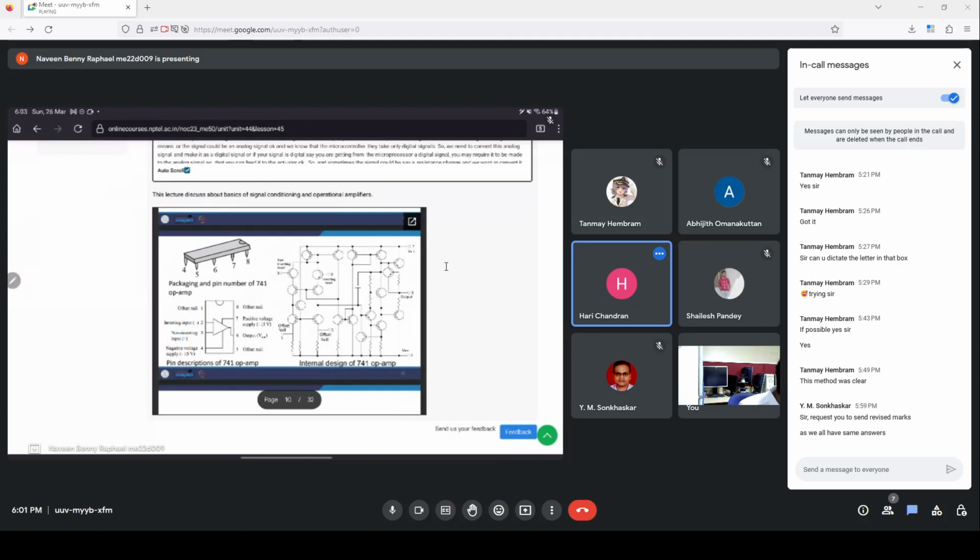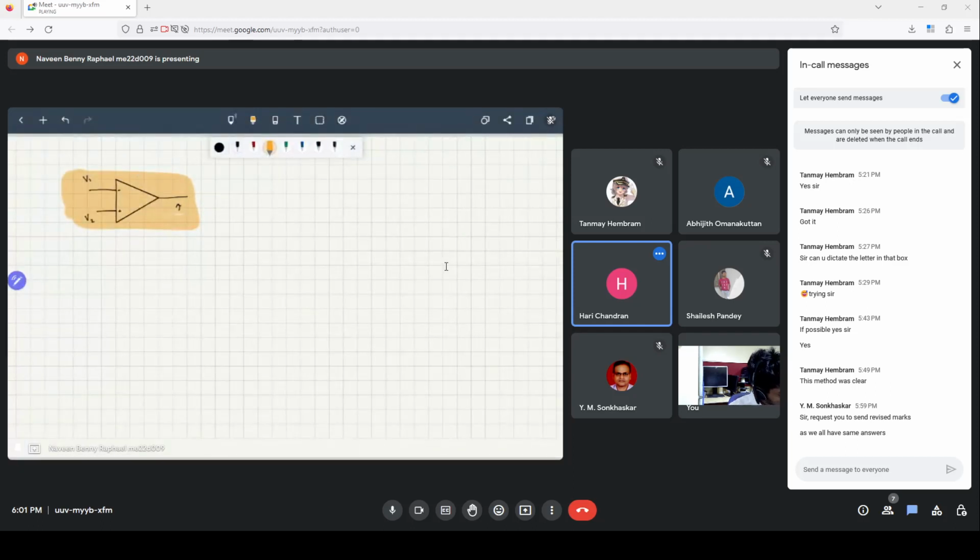If you look, we have the non-inverting input, the inverting input, two offsets, Vs plus, Vs minus, and the output. There are essentially seven inputs to an operational amplifier, and for simple questions we condense it to three: the inverting input, the non-inverting input, and the output.